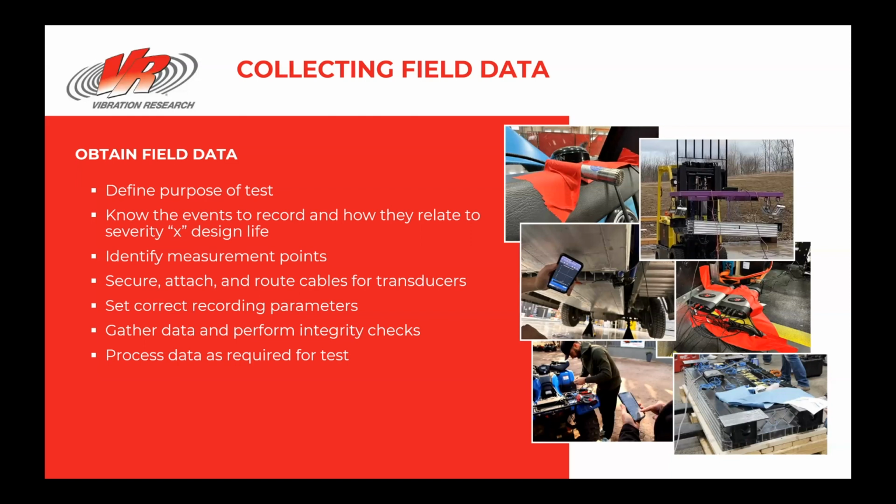Are they to drive and control the test, or are they response? Are they to support a digital twin or some other purpose? We need to secure, attach, and route the cables for the transducers in such a way that we aren't introducing noise to our signal. We need to set correct recording parameters.